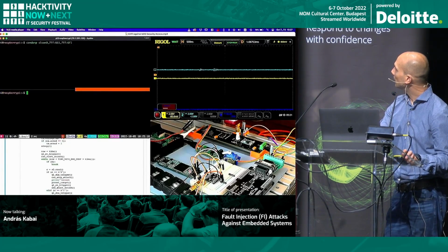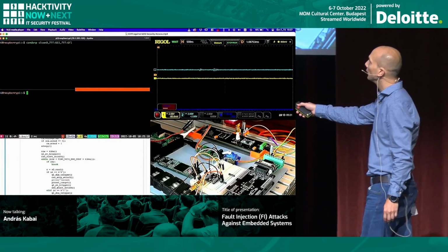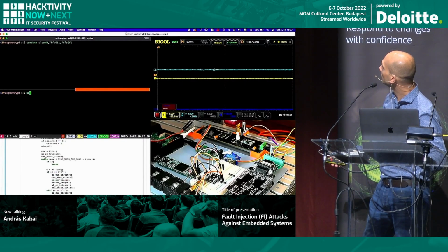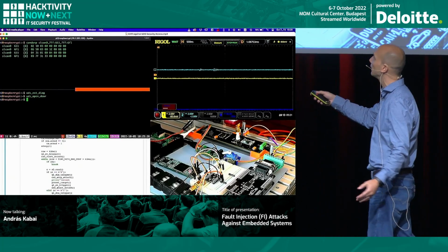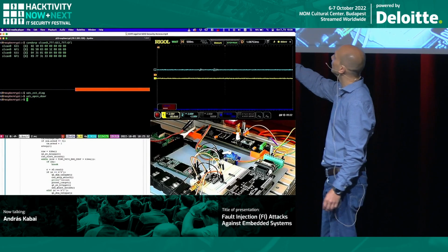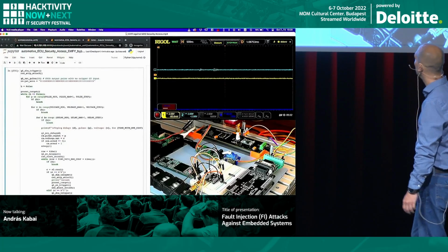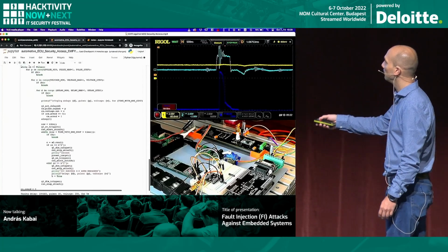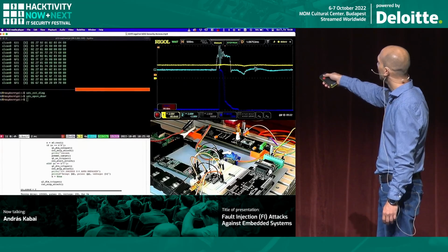So basically the same setup, excluding that we have a terminal here where I'm dumping and filtering for the CAN messages, and you can see that I'm switching to external diagnostic interface and try to open the door with routine control, but as you can see, there is a 7F, which is a good indicator for error code. Because of lack of authentication, it wasn't possible. And by executing basically the attack, you can see how the electromagnetic pulses are injected to the target.